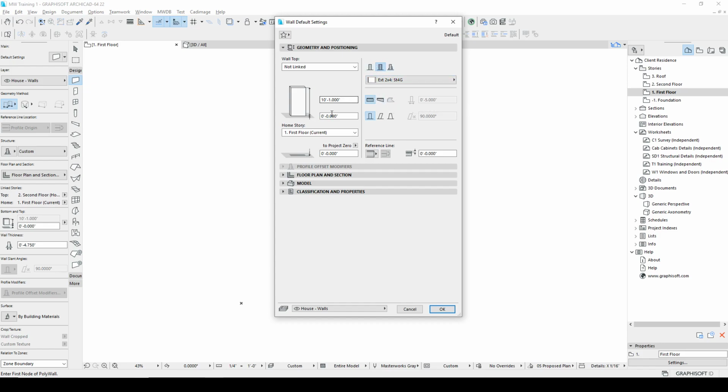Once you decide on your wall type, you have your wall height, you have your wall elevation, you can have a consistent shaped wall where it's a standard width, and when you use the composite wall, that's kind of the default. You can have the wall vary from one end to the other in thickness, which is shown here. You can't do it for a composite wall, but for a standard wall, you can have a polygonal shape. So sometimes that's used for filling in little odd corners and that sort of thing. Almost always I'm using this choice here.